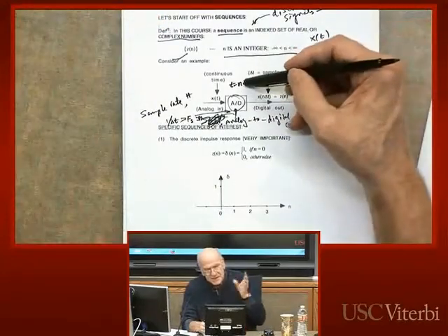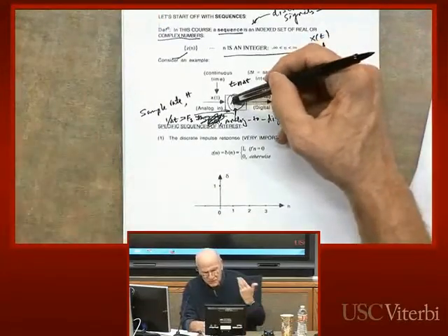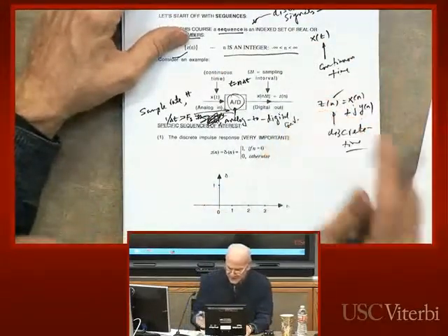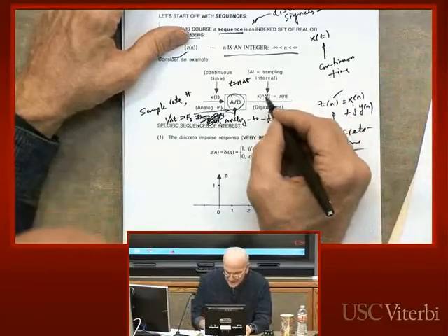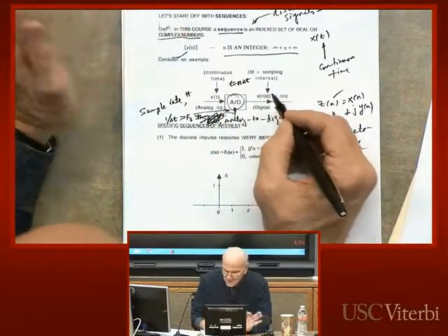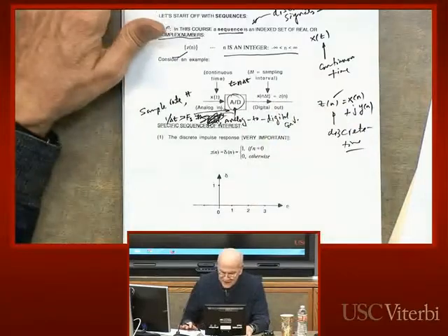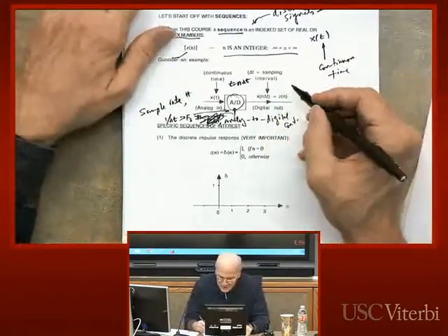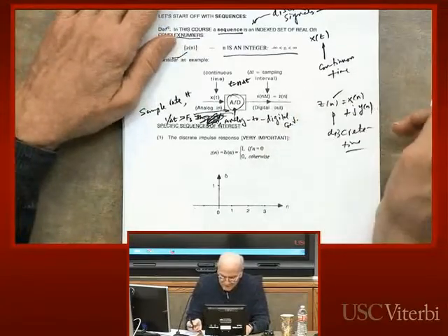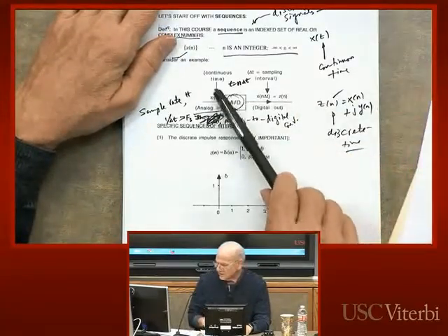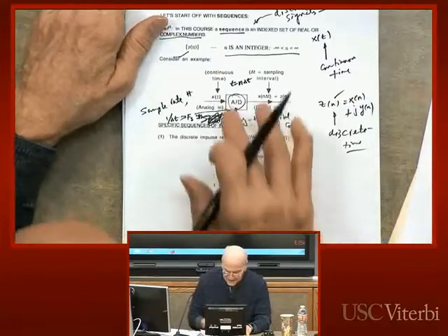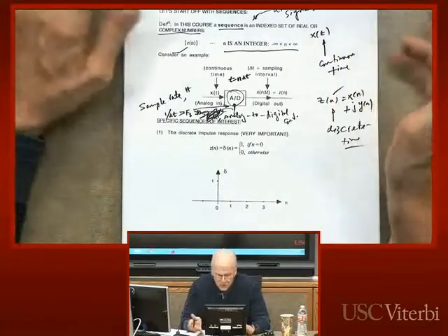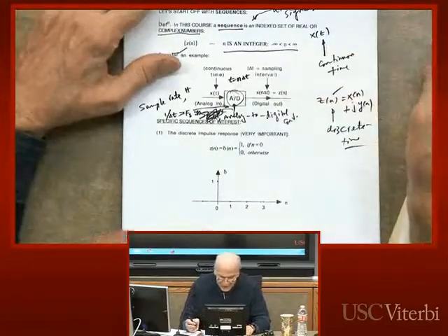That is the time duration between when samples are collected from this A to D converter. And the output of the A to D converter is x of n delta t coming out, see? And that is a perfectly valid sequence that we can use. That's the digital out. So these are very useful devices, these A to D converters, for hardware systems. We'll talk about these in more detail later in the class.